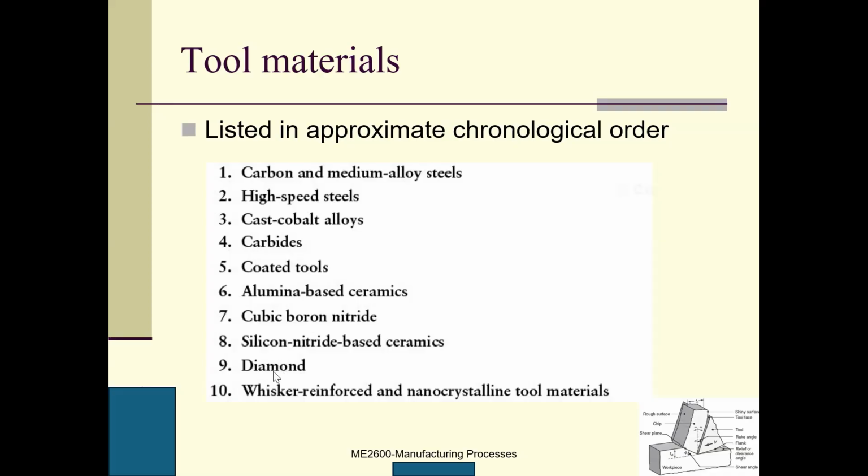But one thing is that diamond is very, very brittle. If there is impact, it is bad for milling or drilling because those are multi-tooth and intermittent machining. A diamond tool is usually used for turning. Turning is continuous, so it can minimize impact.